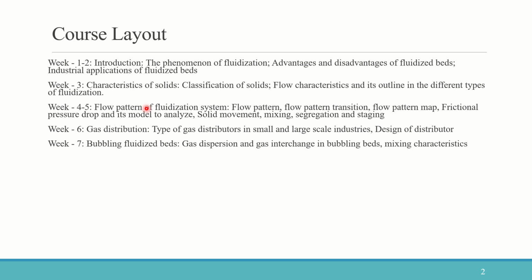And lastly, the important regime of fluidized beds is the bubbling fluidized bed, which we always deal with when we are talking about gas-solid fluidized beds. When we use gas, the chances of bubble formation are quite high, and we need a complete understanding of bubbles in fluidized beds, because only then can we understand the mass transfer and heat transfer phenomena. These bubbles also act as a phase and influence the hydrodynamics of the bed to a very high level. So that is one thing.